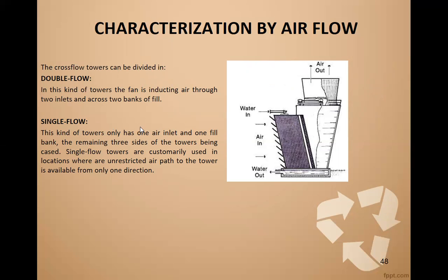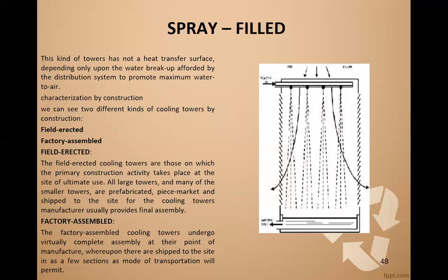Spray fill. This kind of tower has no heat transfer surface, depending only upon the water breakup afforded by the distribution to promote maximum water to air contact. So it has no fill, it is only spray, where the water crosses the air. Spray fill.